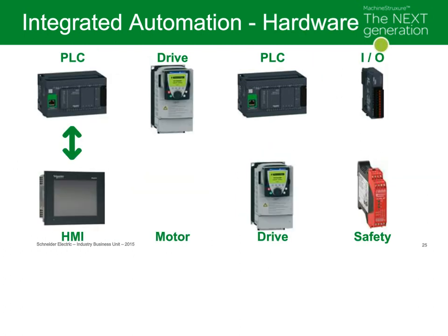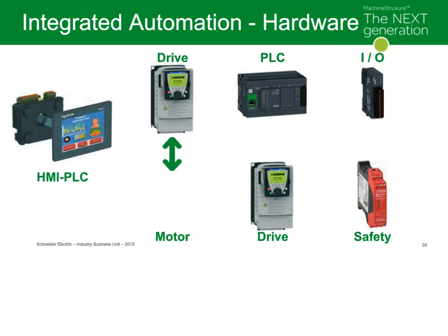So what does integrated automation look like from a hardware standpoint? We're seeing the convergence of separate technologies. We're seeing the convergence of the PLC and the HMI into an HMI PLC combo unit. It's not completely novel in the industry because there are quite a few manufacturers out there that are making HMI PLC combos. What Schneider Electric has done, though, in this HMI PLC combo unit is they've also released one that has a 22 millimeter push button mount. So you're able to, from that, just punch out what you would for a push button and mount your HMI, which of course makes it a lot easier to get that up and running.